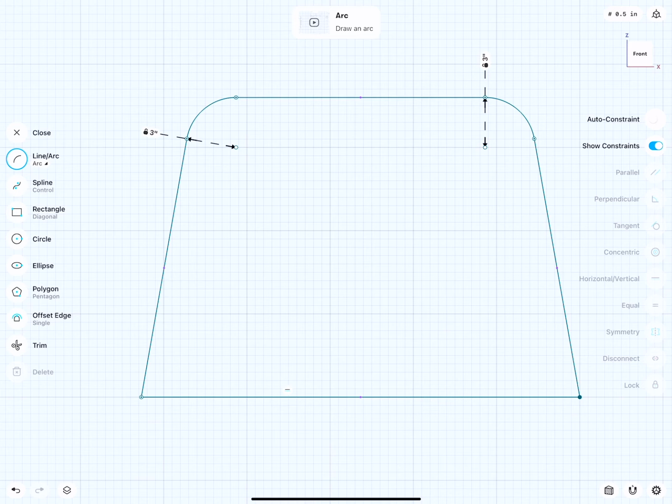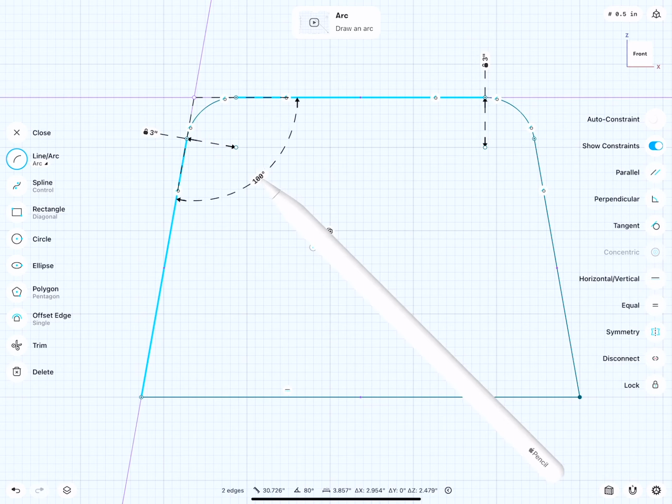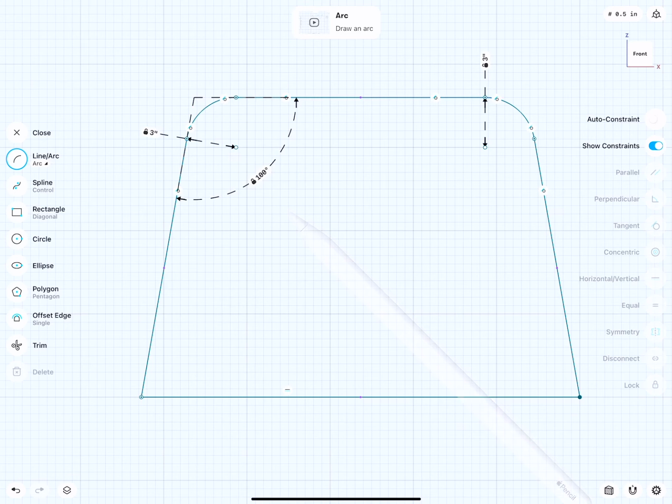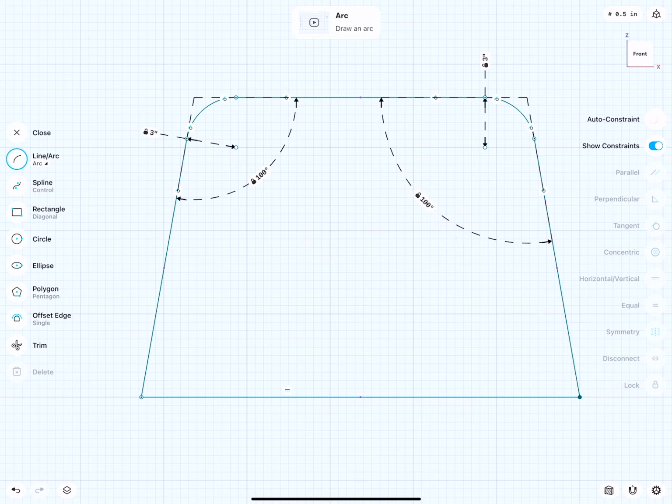But when I go back and take a look at the sketch, I can see that a lot of elements are gone. So this is 3 inches, that is good, but the tangency constraint is gone. So I quickly will add the tangency constraints back into the sketch. I can also now select the 2 lines and add back the angle. Very nice.